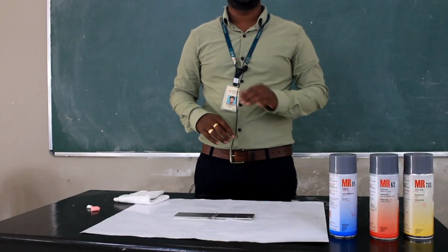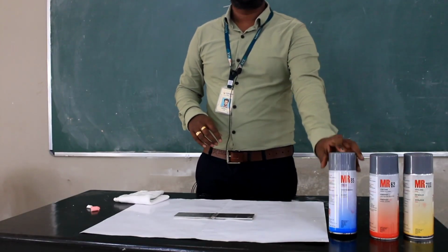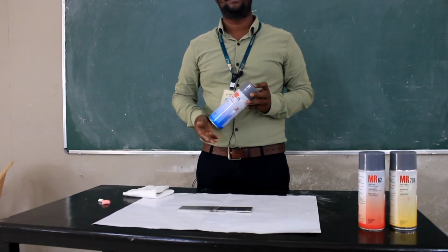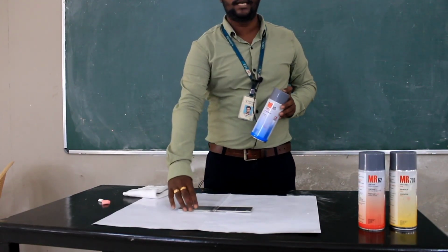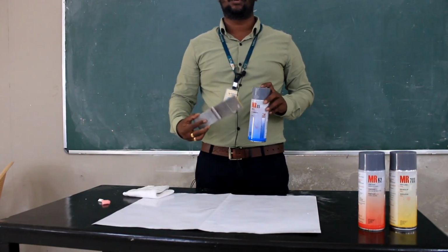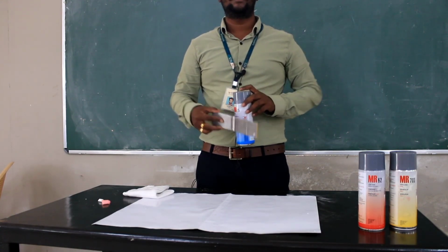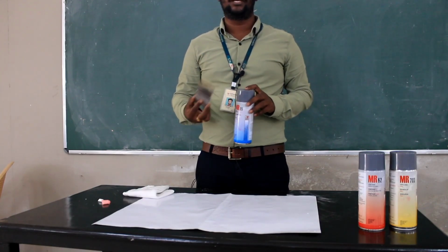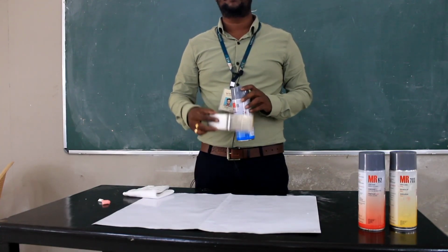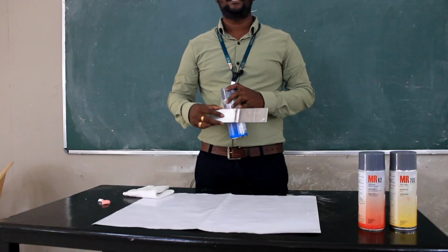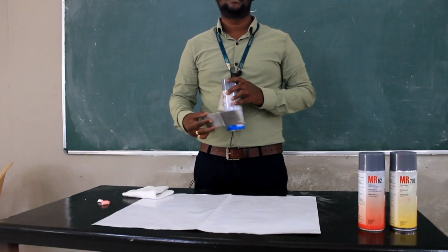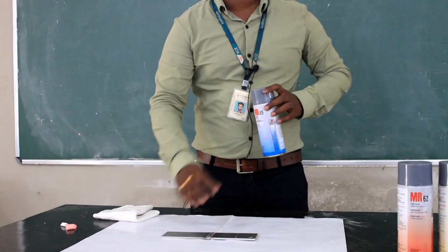The first stage of liquid penetrant testing is applying the remover. The purpose of applying the remover is to remove the dust particles present on the welded samples. Why? Because the samples are used for industrial purposes, and in industry we have dust, paints, and grease. We have to remove all the dust particles, otherwise the dust particles will also show up as defects. So the first process is called the removing process.